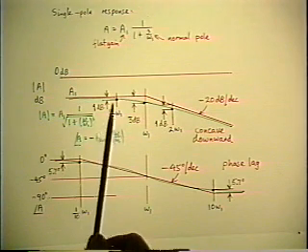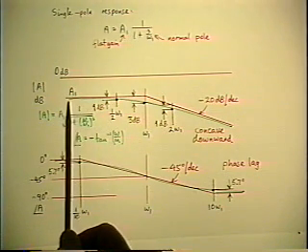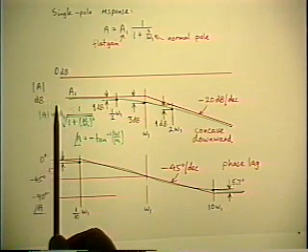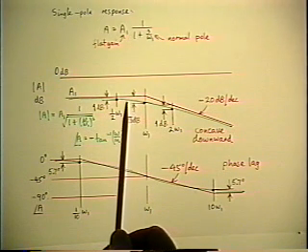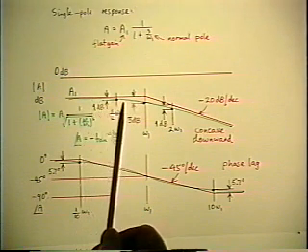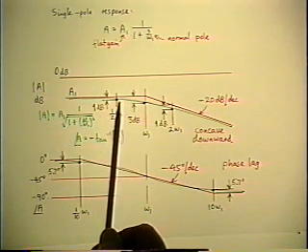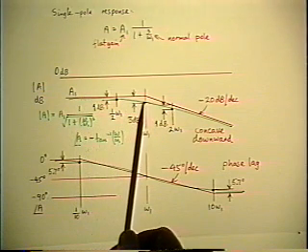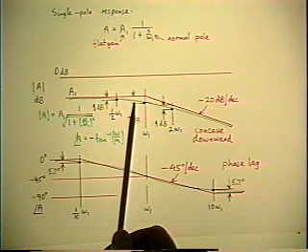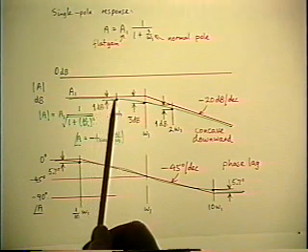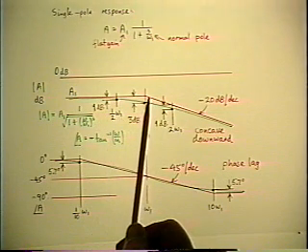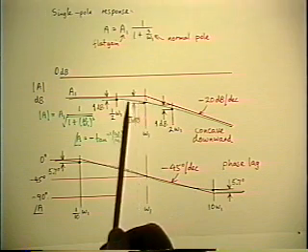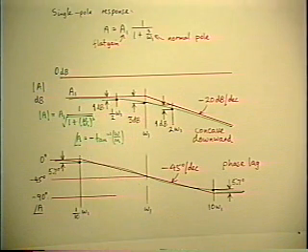Another way to express that is imagine yourself standing on the frequency axis and you start walking along the axis towards higher frequencies. But there's a fog around you and you can't see very far ahead. All you can tell is the slope of the ground under your feet. And the slope seems to be increasing. And the question you're asking yourself is, the slope's getting bigger, when am I able to say there is a corner up ahead that I can't see in the fog? So the 1 dB down point is that criterion.